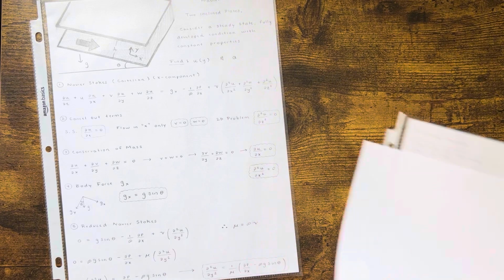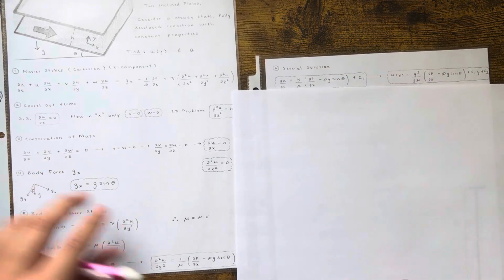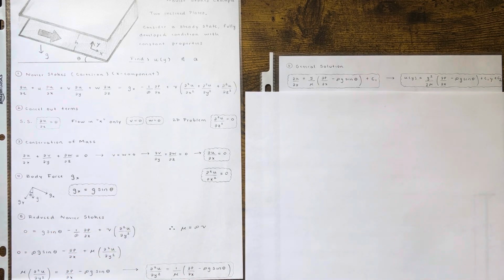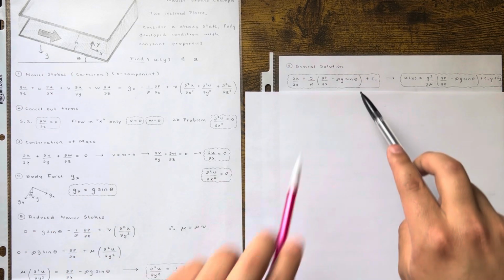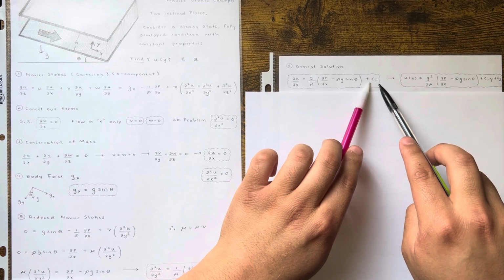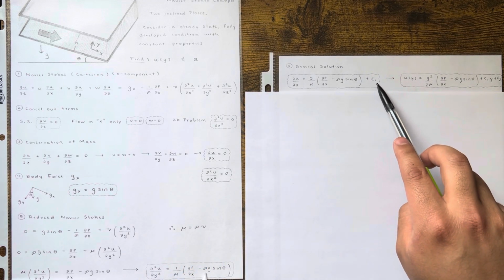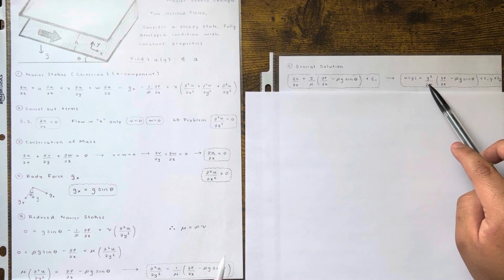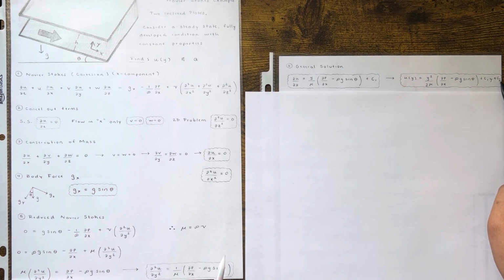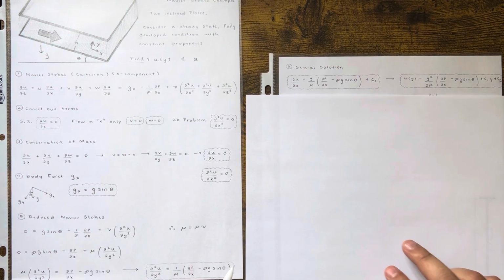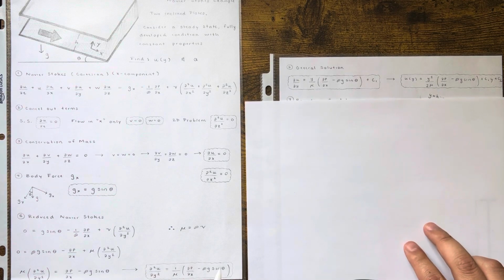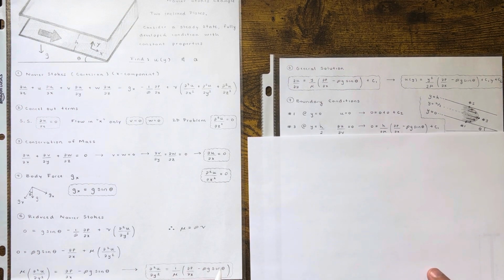And let me show you this right here. So when I did that, this is what I'm dealing with. Integrate this with respect to y, that becomes y over mu, and then plus c1. And then integrate it one more time to get the velocity profile general solution. It's just y squared over 2 mu plus c1 y plus c2. So now that I have that, I need boundary conditions, because I need 2 of them because I have c1 and c2. So 2 boundary conditions, let's see what they are.